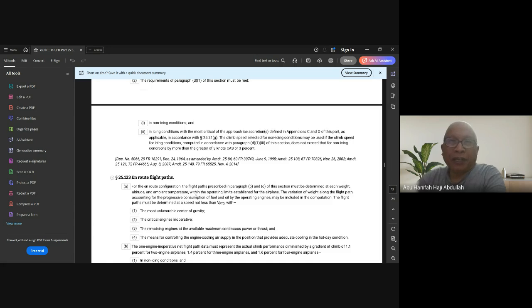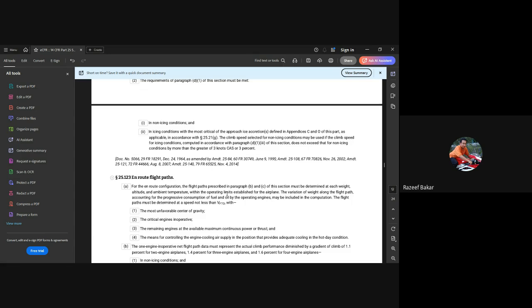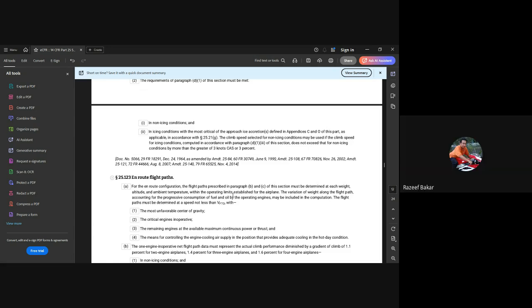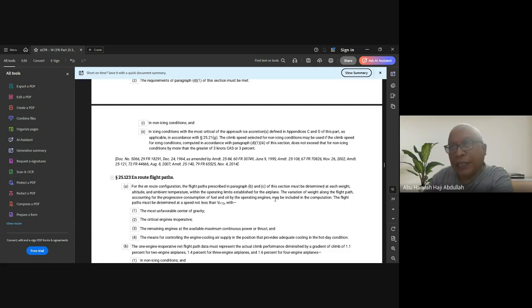But FAR Part 29 does not allow that. That's why we did not accept the aircraft. But people may say, okay, what's the problem? Now we've got 171 in Malaysia and they all still fly. So we can take the argument, but again, as we do the engineering, we need to provide hard evidence. That's a problem. So the best way is redundancy. The better redundancy, but again, there's something people miss.